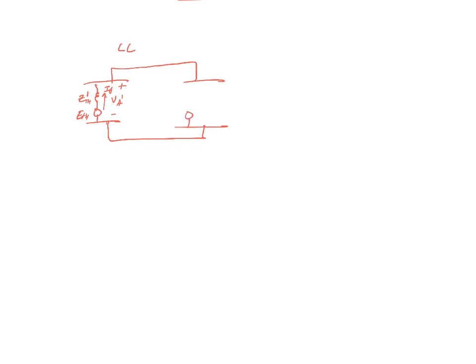Oops, I started to draw that. That's incorrect. I do not have any voltage source. I just have a Thevenin equivalent impedance here with our IA2 and our plus to minus VA2. If you have an impedance in your fault, which oftentimes in a line-to-line and a double line-to-ground you don't, you would just include that here as your fault impedance.